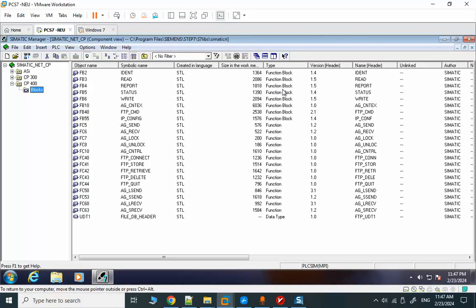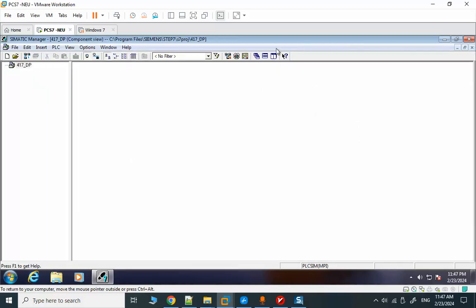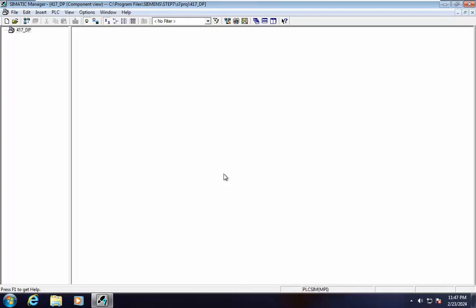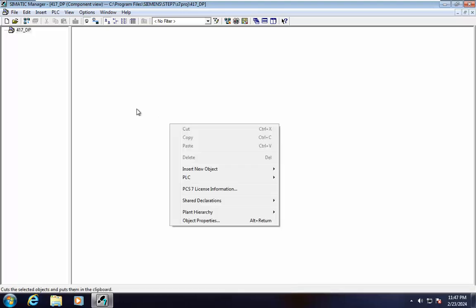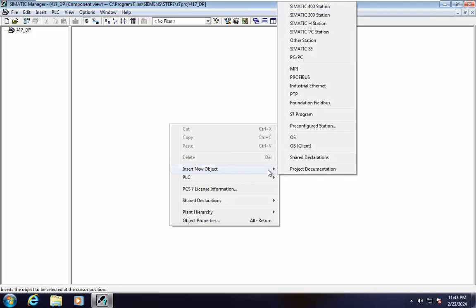So there is another possibility. You can perform other connections. If it's not master slave, there are other possibilities over Profibus, like S7 connection and FDL or others. If you read the SIMATIC NET documents or check the sample examples.